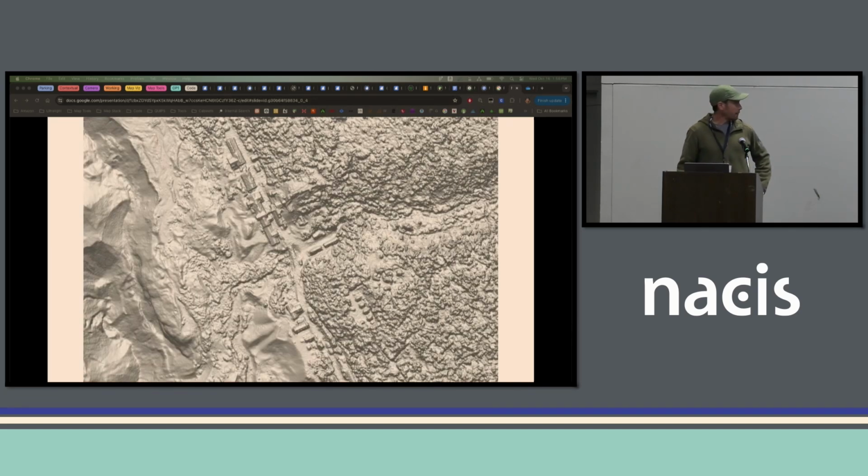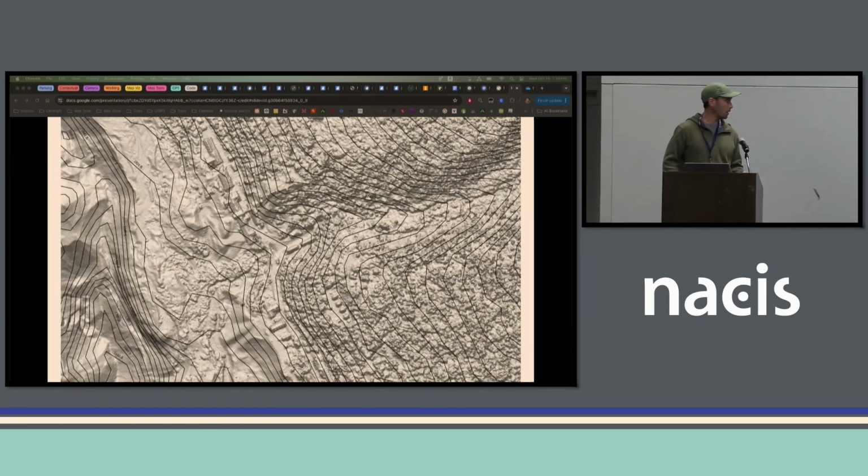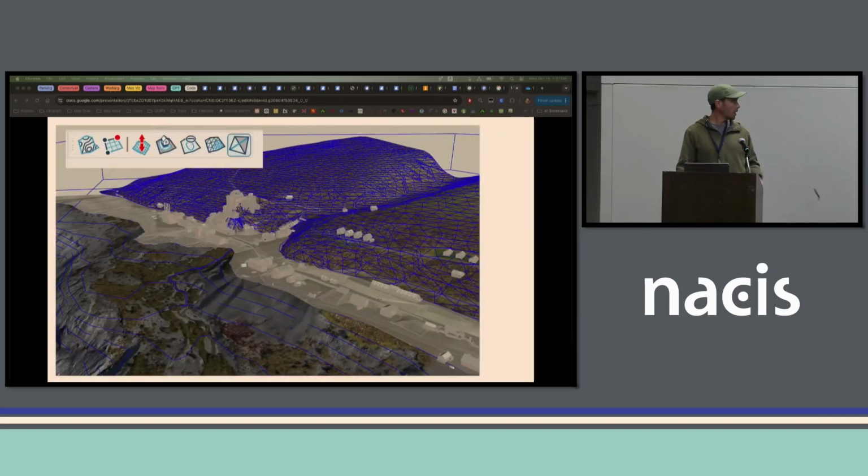And then finally for the modeling is going to be the terrain. It's interesting, they have lots of terrestrial LiDAR, no aerial LiDAR. This is actually a stereoscopic 5-meter DEM or digital surface model that was created for the site, but much too busy for the purposes here. I need a really simple terrain model. So I simplified this as much as possible down to 20-foot contours to be able to export that into SketchUp.